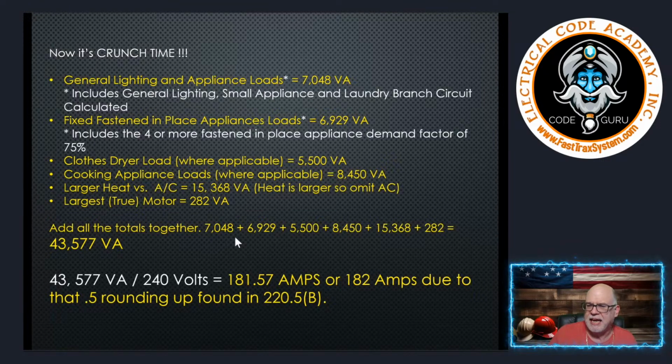And it's okay. Now, in the 2023 edition, you've got a nifty little table. In the 2020, I think you do as well. Prior to that, you had to go to Informative Annex D, under the D7 example. But it's basically called the 83% rule, and it's 83% of what's marked on the actual breaker. To keep it simple, it's the breaker or fuse rating.